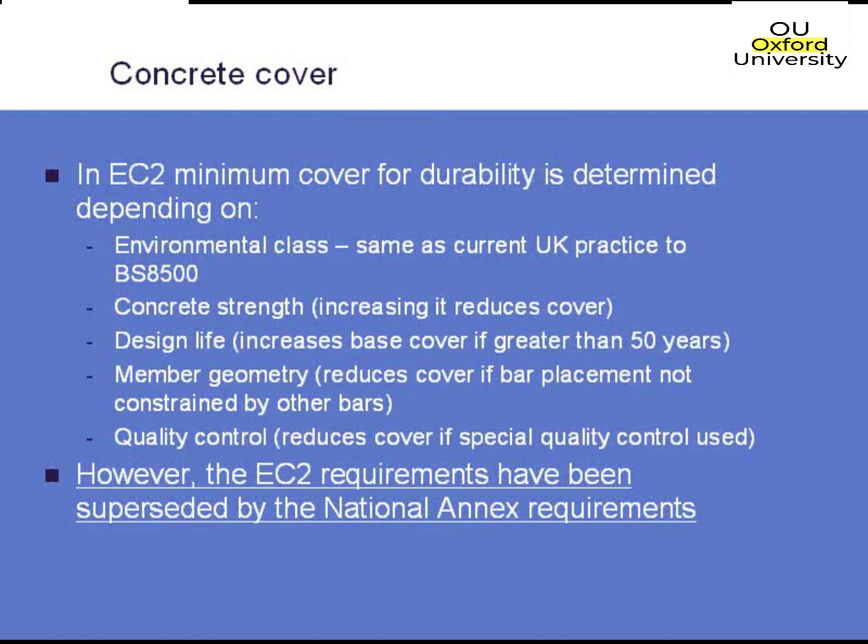It's only really if you come on site, the contractors put all the reinforcement in at a reduced cover, and you then come in and you can justify using that clause, because then you know exactly where your reinforcement actually is, and you can say, yes, it is exactly there, so we can justify reducing the cover requirements. But if you're just doing a design in the design office, I would stay well clear of that. It's just not a very good idea to use unless you can justify the special quality control, which, as I said, hasn't been defined.